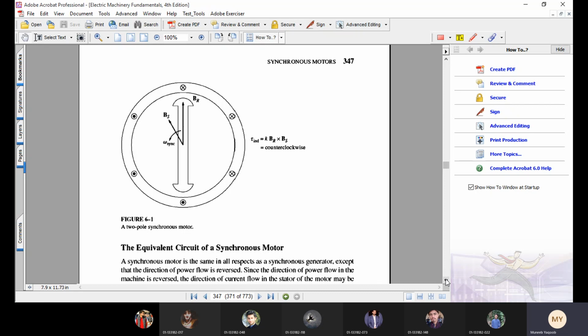But three-phase motors start automatically due to the rotational magnetic field produced by their stator's winding. Since the synchronous machine also has the rotational magnetic field of the stator's three-phase winding, it is not started by a special starting technique; rather it is a self-starting motor.